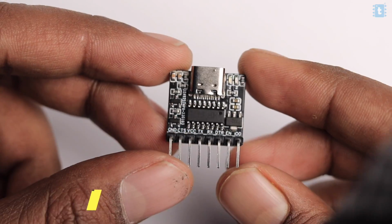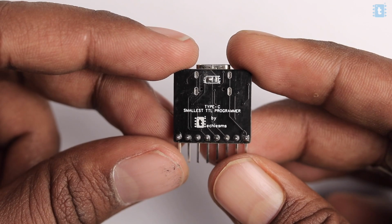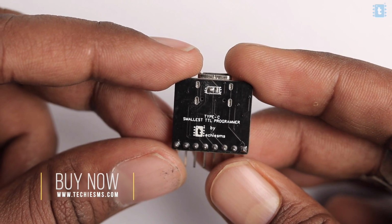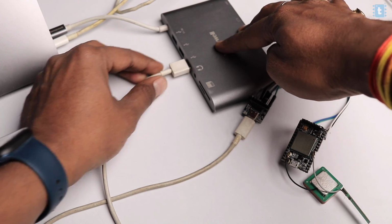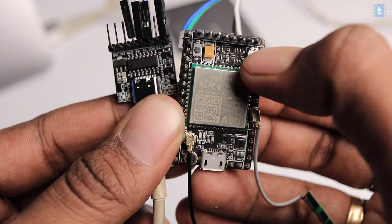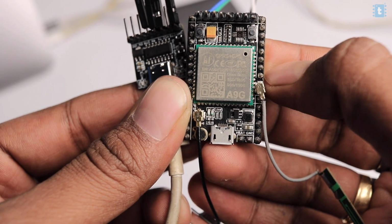So after changing its firmware to Micropython, we are ready to install the Micropython scripts in it, but before that, we need to do the programming connections. Yes, you can't program the A9G board directly with the built-in micro USB port. Rather, you will need a TTL converter. So here I'm using the smallest TTL programmer made by team techiesms, which is set to 5 volt logic level. If you want to buy this programmer, its purchase link you can easily find in the description of this video. We made the connection between the programmer and the A9G board according to this connection diagram. After that, I'll connect the programmer with my computer and press and hold the power button on the A9G board for 2 to 3 seconds to power up this board. Now we are ready to jump onto our computer and install the scripts onto the A9G board.